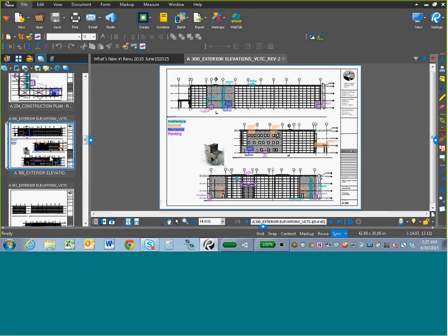So the story of Sets 3.0 is that you can run document comparison straight from the Sets panel itself. All you have to do is right-click on the document and see that you get this compare documents or the overlay pages. So that's, again, a really nice way to utilize the sets, but also that compare documents functionality. Sets 3.0 is going to make it so much easier to view, organize, and utilize your single-page PDFs. So that's Sets 3.0, and now that we've got our files organized, let's talk about the enhancements to the tools that we use to mark them up.